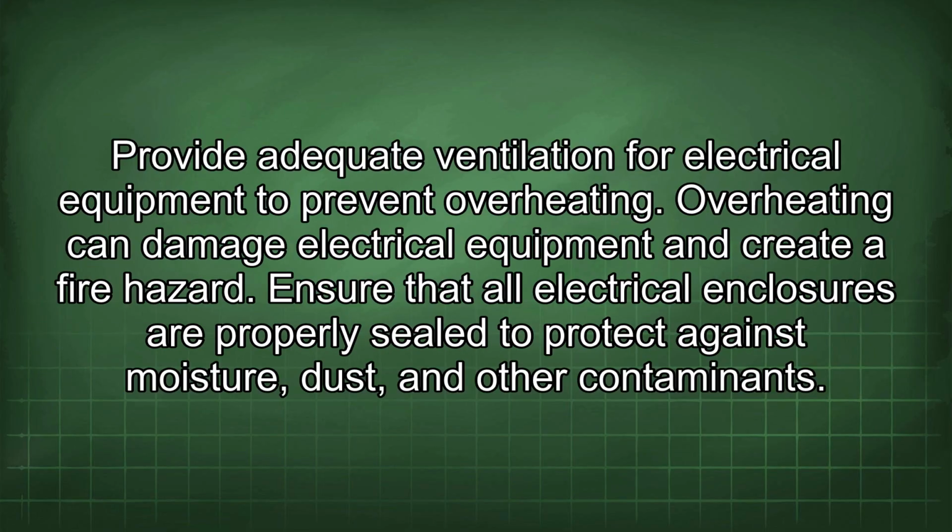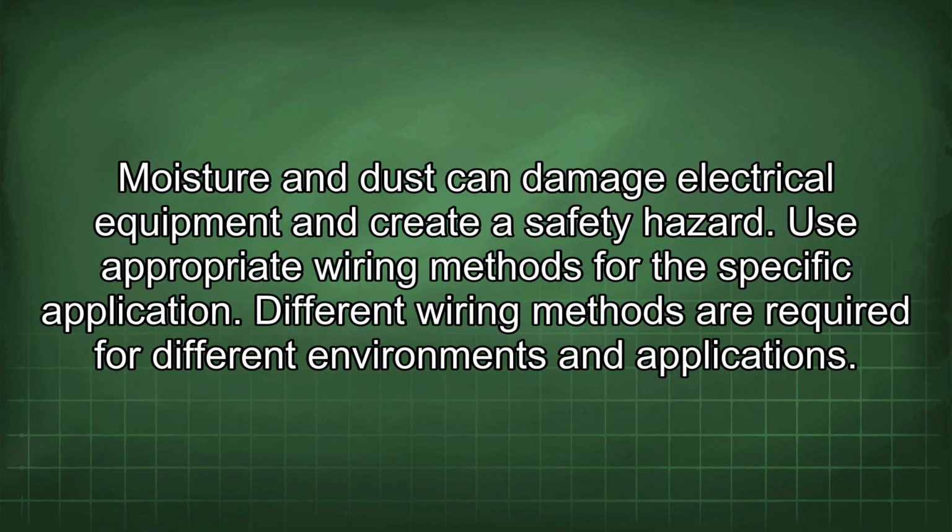Provide adequate ventilation for electrical equipment to prevent overheating. Overheating can damage electrical equipment and create a fire hazard. Ensure that all electrical enclosures are properly sealed to protect against moisture, dust, and other contaminants. Moisture and dust can damage electrical equipment and create a safety hazard.